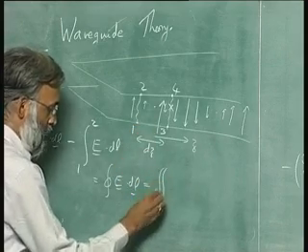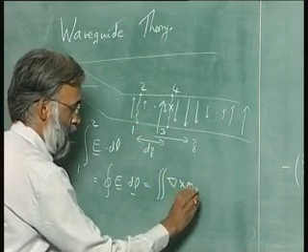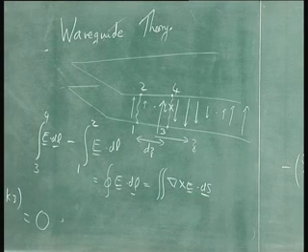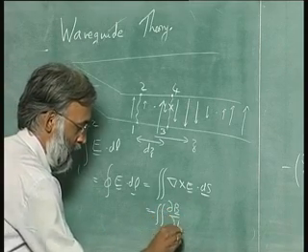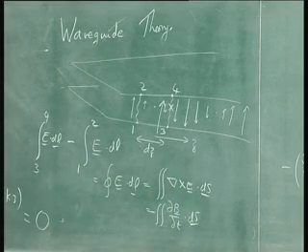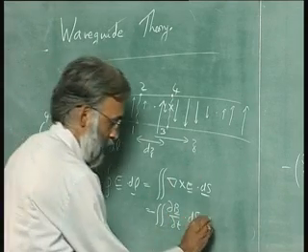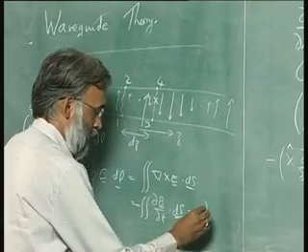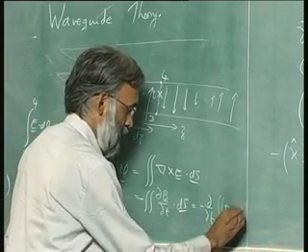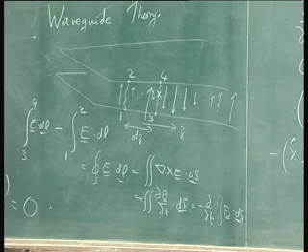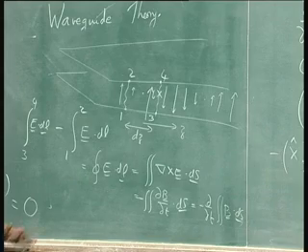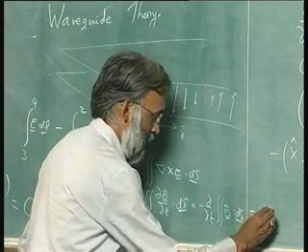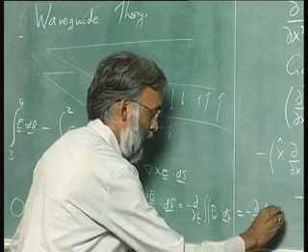That is nothing but surface integral curl of E dot ds, which is, apply Faraday's law, minus del B del T dot ds. I will pull the del T out. It is minus del T of surface integral B dot ds. But we know that surface integral B dot ds is nothing but flux, and flux is Li. So we can write this as minus del T of Li.